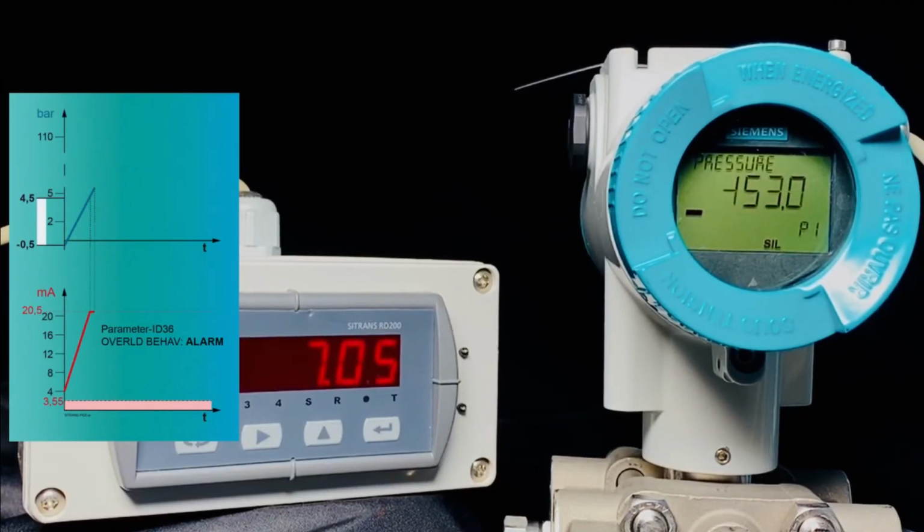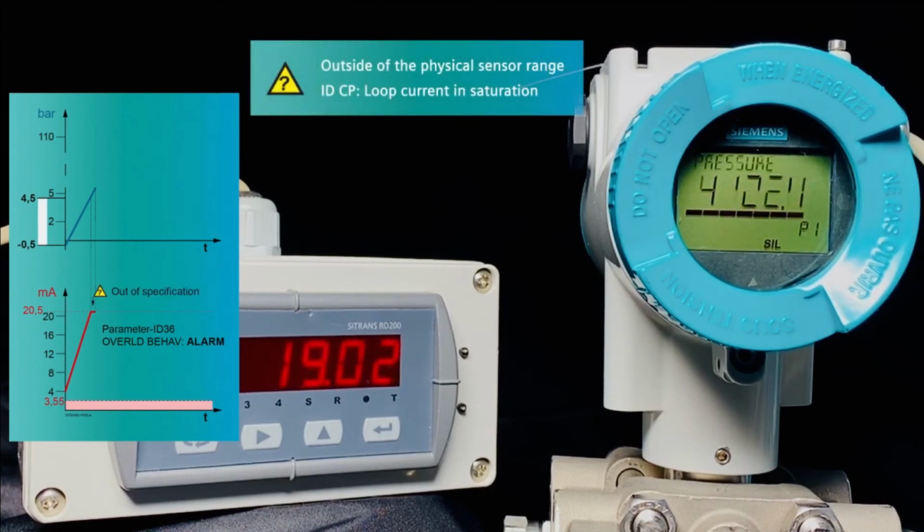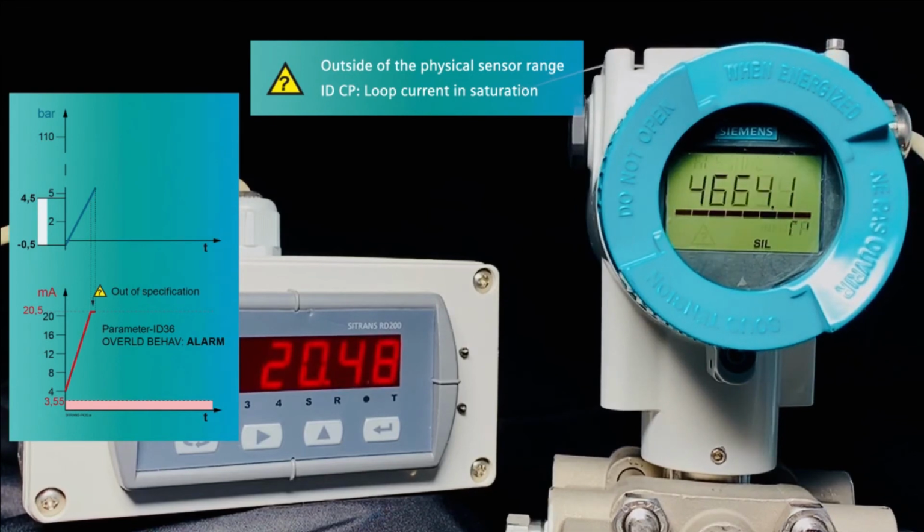As soon as the current goes into saturation, the symbol triangle with question mark for out of specification after NE 107 appears. Alternating with P1, info CP appears. CP stands for loop current in saturation. For this and more detailed information, refer to the chapter Diagnostic Messages in the manual.